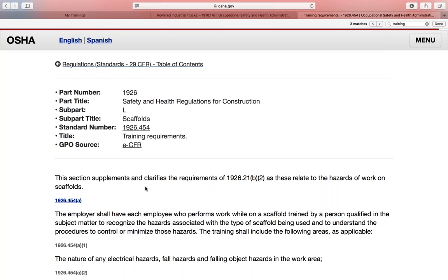So we're talking about safety precautions that are unique to aerial lifts, and we have to go ahead and discuss them and cover them with employees. Each manufacturer is going to have certain specific precautions, and I'll show you a couple examples of those. And then, of course, that's where you see OSHA 1926.453, which is what we just talked about, points out all the requirements of an aerial lift.